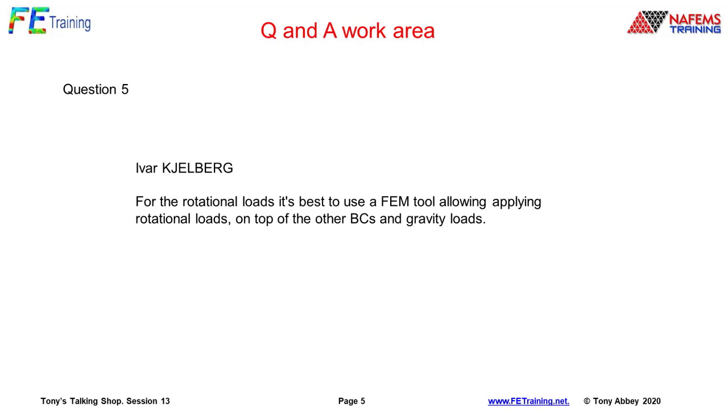Ivor says, for the rotational loads, it's best to use an FEM tool, applying rotational loads on top of the other boundary conditions, gravity loads. Yeah, I agree with you. The unknowns, you've got the free body diagram, you've got your rotational accelerations. Just apply those directly and let the FE analysis figure out the distributed body loads is a good way to do it.